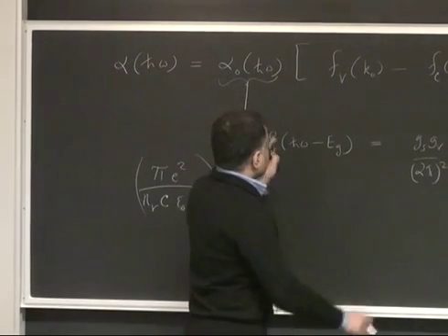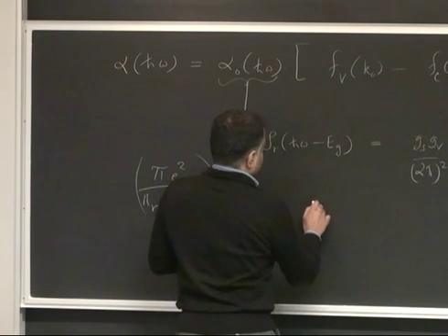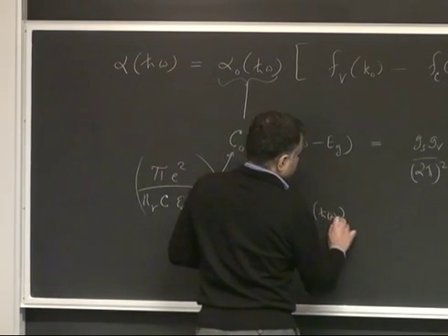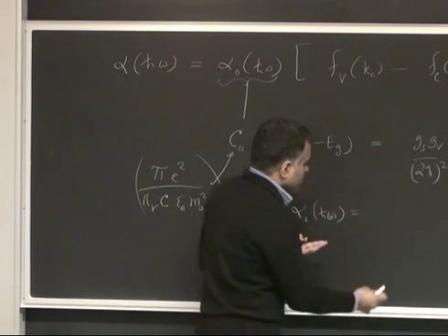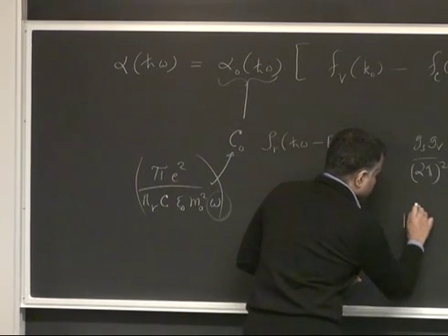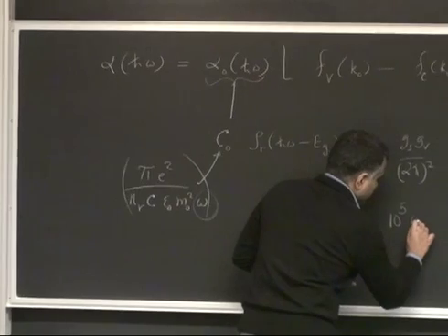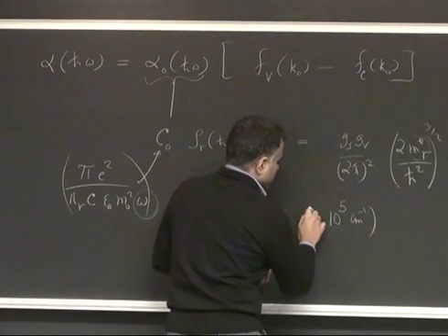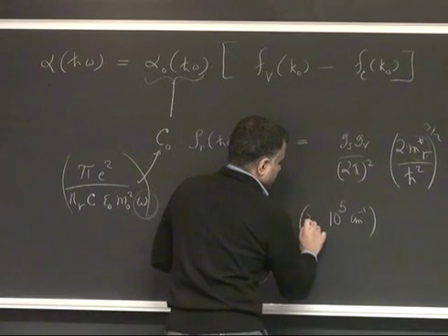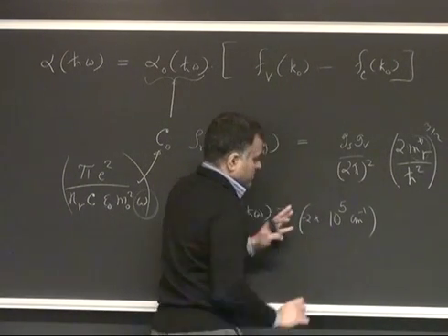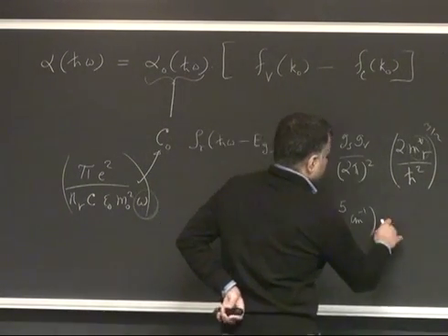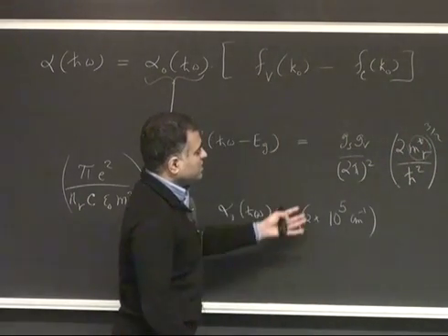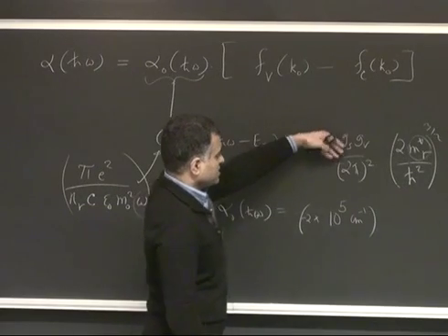Okay, so when you combine these quantities, let's just look at the magnitude of the absorption coefficient. You will get of the order of 10 to the power 5 inverse centimeter, and I think there's a 2 or a 3 here. Let's call it roughly 2 times. And then I think you can see how all these parameters enter. If you have valley degeneracies and all, they'll enter there.